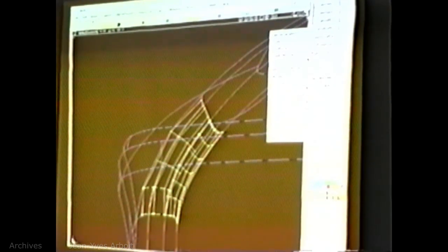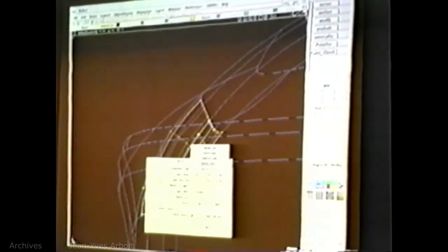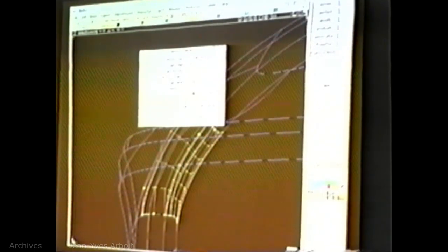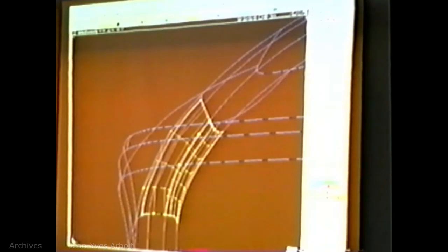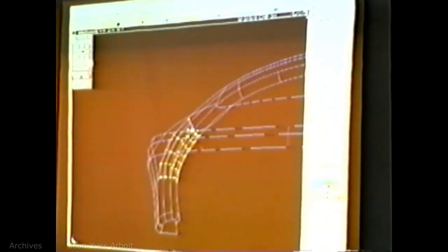So all the surface evaluation tools, such as highlights, horizon, contour, curvature, all of these have both a method by which you get the curves on surfaces, but also now there's a visual. And if you use visual, they'll be much faster. And in the same way, the evaluation check draft tool. And I don't really want to have any of those little green and red dots right now. Actually, it might be that I've got to put one in there. I had some problems with this before. But I want to show the parting line. There we go. Let's see what surface it is.